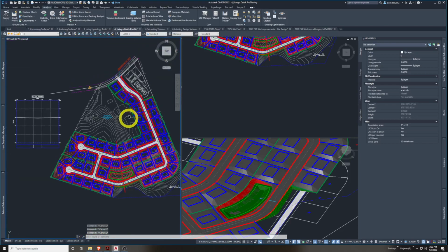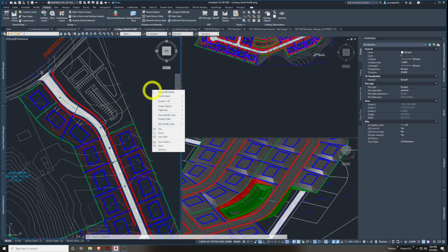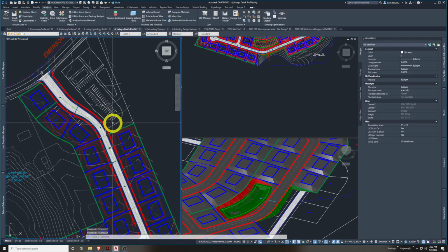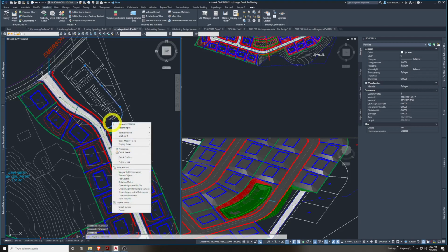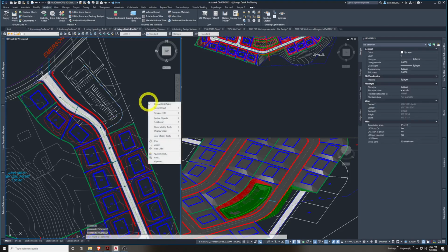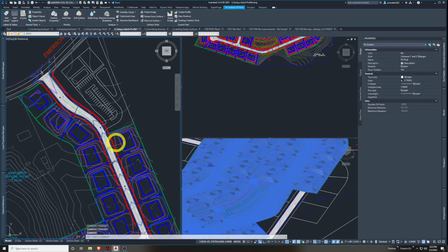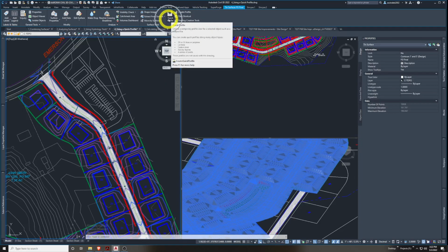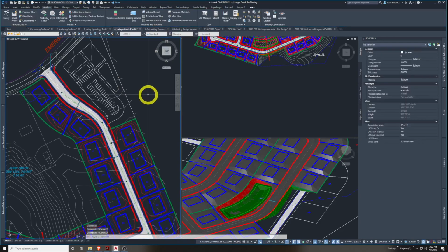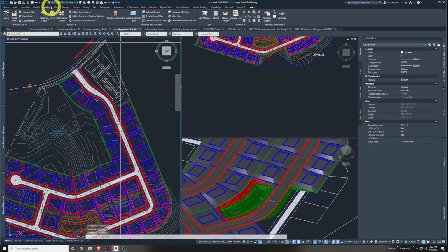So this one you can get quick profiles any number of ways. You could literally click on almost any object and right click and say quick profile this way. You have to have something selected. You could pick certain Civil 3D objects and say create a profile quickly on most all of them. Okay. Or you can not have anything picked and go to the Analyze tab and also do it. So I'm on the Analyze tab and I'm going to run a quick profile this way.